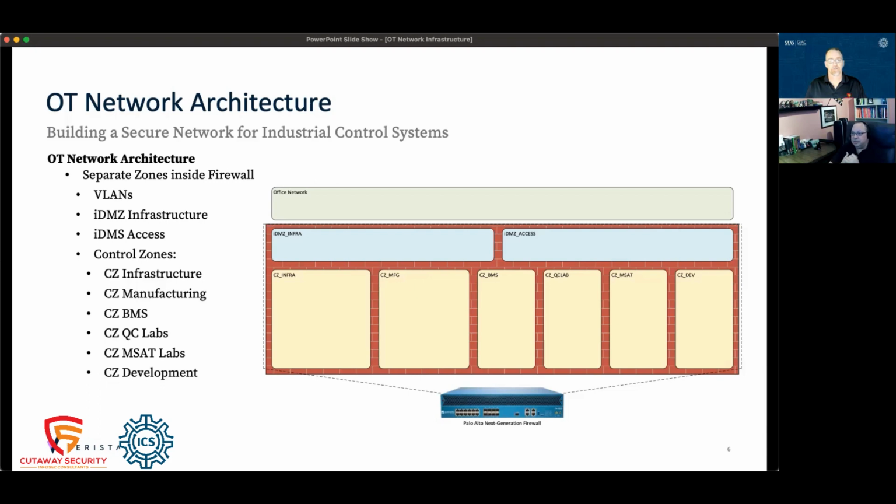Those are your conduits. So the firewall that you're using to separate everything from your plant network, that's the same firewall that's managing all of your level 3 environment to include the DMZ. Yes. Okay, that makes sense. And obviously this is probably a dual firewall pair for primary and secondary. Active, passive, yeah, exactly. Primary and secondary. Could you put a firewall here and a firewall here and have your DMZ in between? Absolutely, you can.